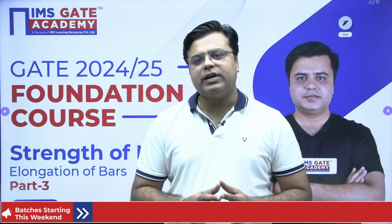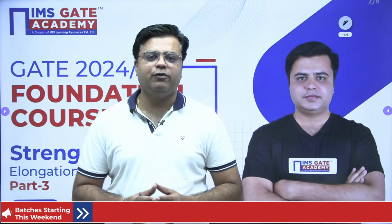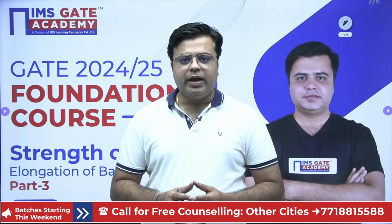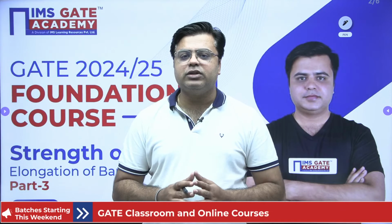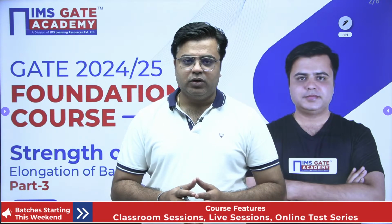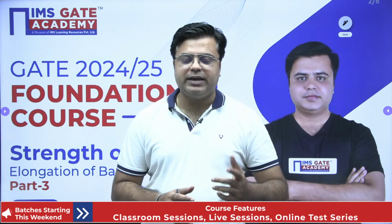At the end of that session, we also discussed, if any bar is hanging under its self weight, how much amount of deformation that bar will undergo, and also we discussed that deformation due to the self weight does not depend on the cross sectional area. So it doesn't matter whatever is the cross sectional area for a prismatic member, right?